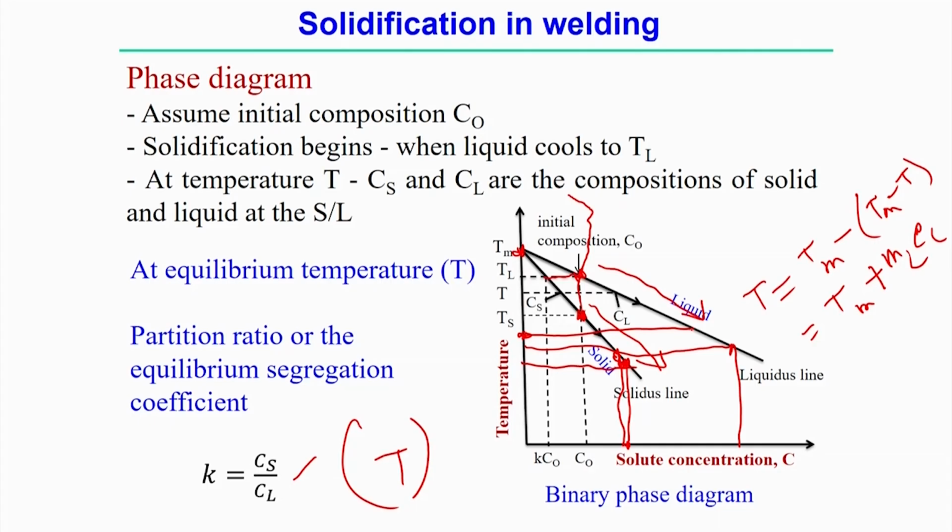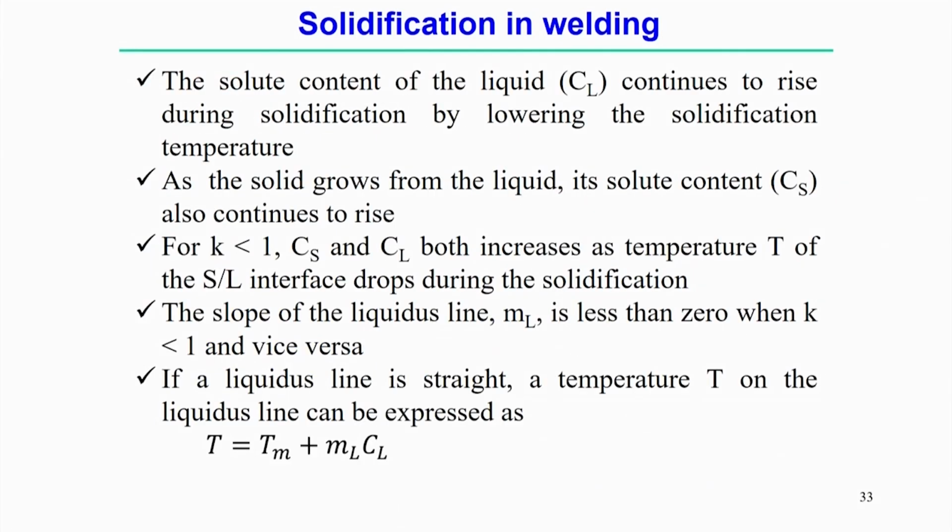Mathematically, this is equal to that slope into that content CL. So, if the liquidus line is straight, not curved here, then a temperature T on the liquidus line can be expressed like this.